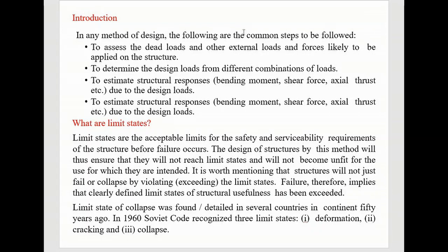Now in all designs, the limit state concept is followed and will be followed, but till now some special structures such as water tanks and chimney designs follow the working stress method. Sorry, not working state, it's the working stress method. So they are following this, but everywhere else we are following the limit state method.